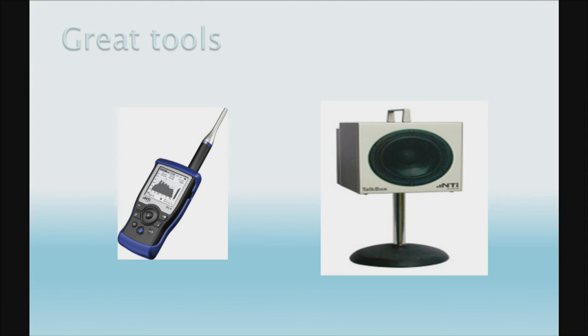There's also NTI. They make them a little bit more expensive, but if you do a lot of your own stuff, you know, little spectrum analyzers, the Talkbox. A lot of times what they do with that, they put the Talkbox speaker one meter away from your microphone, run it for a couple minutes, and analyze what they're getting out at different test points. And that's another thing that's really important on the audio. Again, you can spend several days talking about this, but specify where you want these tests to be taken within a room. Small room like this, we might do one here, one over there, but in a big 100 or 200 seat auditorium, we'd want to get real specific on where we want these measurements done.